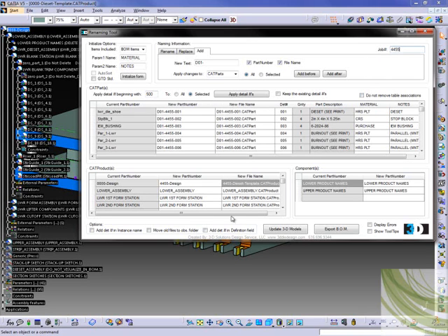Last thing I want to mention before we move down to the lower portion of the form is you can select Do Not Remove Table Associations here. Anytime we change a material or a note, for example, or any parameter that's attached to a table, there's no guarantee that the value exists in the table. So what it does is it actually goes in and deactivates the table and then changes the value. If you want to make sure that the value exists in the table and that somebody can't change it, you can select this Do Not Remove Table Associations, and what it will do is it will attempt to change it to that value if it exists in the table, and if it doesn't, then it won't. So we'll let it go ahead and remove them for right now. It's not a problem on this particular application.